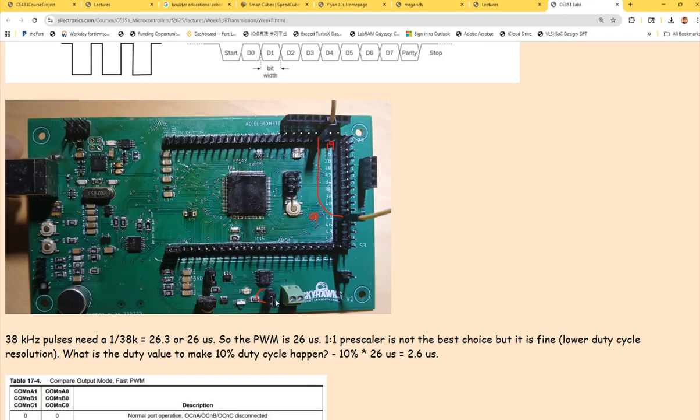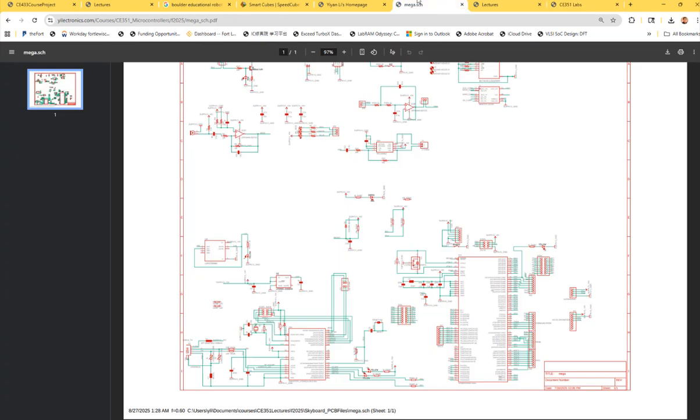However, if you probe this little jumper, you see there's a bare metal on the top. That's designed for probing, just to let you know, okay? Because whenever you put a jumper on two pins, the pins get covered, but a lot of times people still want to probe them. That's why the little jumper has bare metal on the top, so you can use the probe's hook to hook onto the top. You put the probe on the top over here, and it's not showing the PWM. What's happening? It's the same signal line, right?